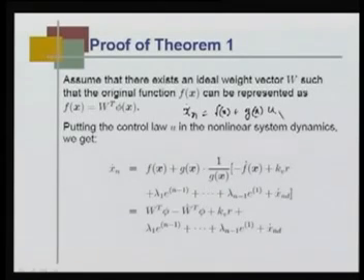So, now you replace this u here. What you get is x n dot, then f x is here plus g x, and u is 1 upon g x times these terms that were inside. So, doing that, what you get is f x, which is w transpose phi x. It is assumed that there exists some basis function, a vector phi, multiplied by the weight vector w transpose.